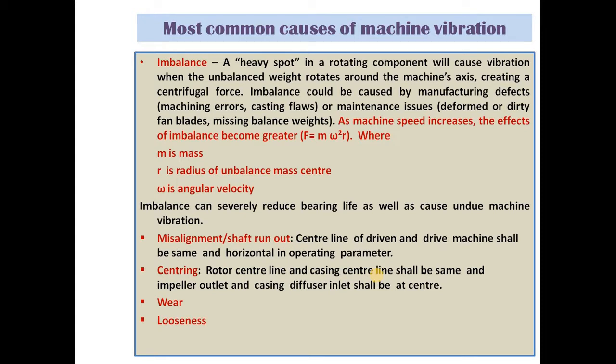Then wear and tear: if a machine is running continuously for a prolonged time, then due to natural wear and tear, clearances will increase, and that will increase the load, and as a result bearing vibration will appear. Looseness is also similar to that. If looseness is there, then certainly unbalance will come and vibration will appear.